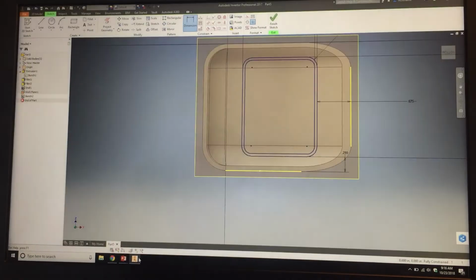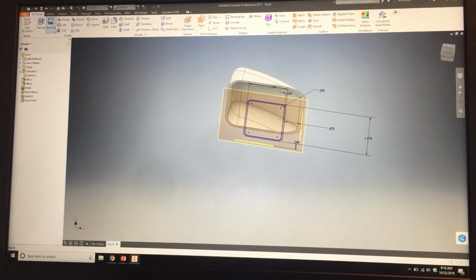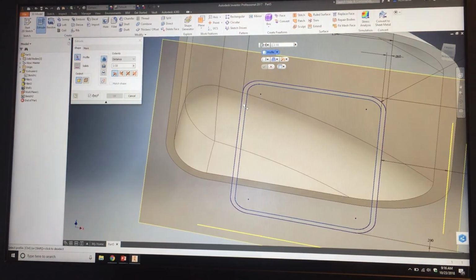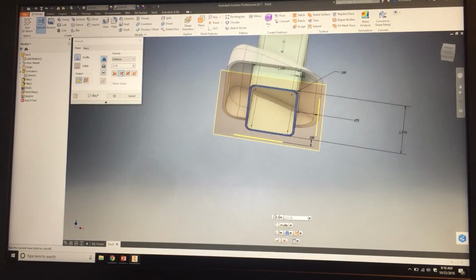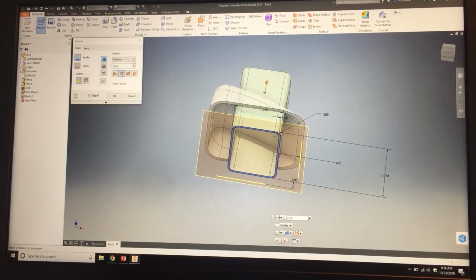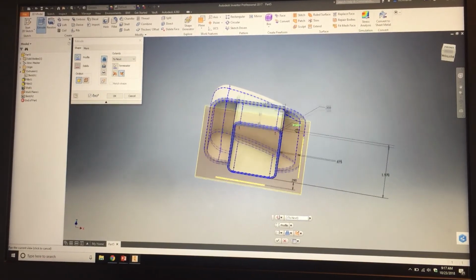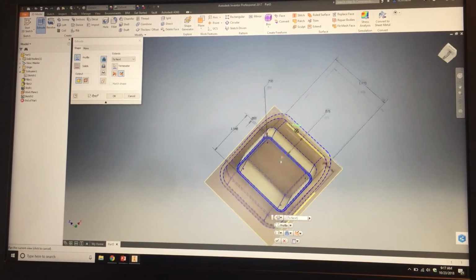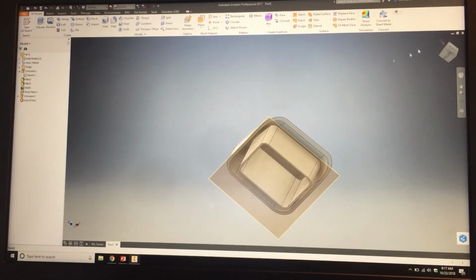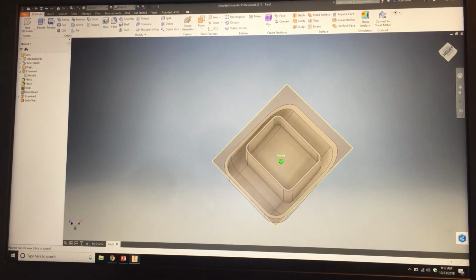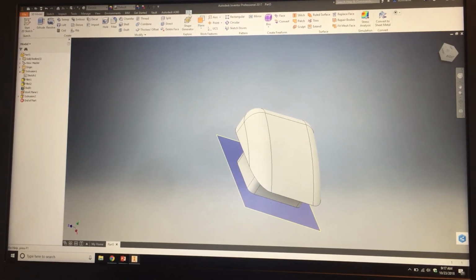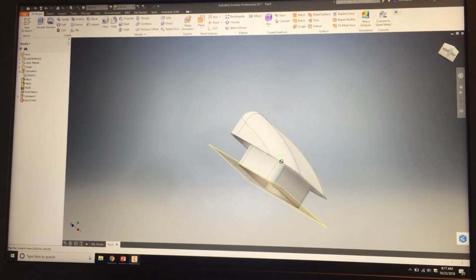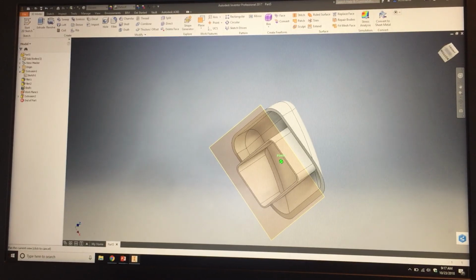So we're going to do an extrude now. So finish the sketch, extrude, and we're going to extrude that surface, and we're going to go the opposite direction. Now, right now we have it selected as distance. You can have two next, so it's going to extrude it till it touches the next surface. So I go ahead and click OK, and that is there. That's the windshield. I could actually change the type of the surface and make it see-through, but there's your windshield for the most part.